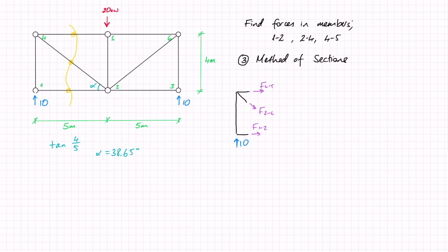If I look at this structure now that I have to solve, I can see that there is only one unknown, that is 2,4 in the y direction. So I'm going to start off with that. I'm just going to remind myself what my positive directions are, because I want to be consistent with them as I go through this. So I'm going to start with Fy equals 0.